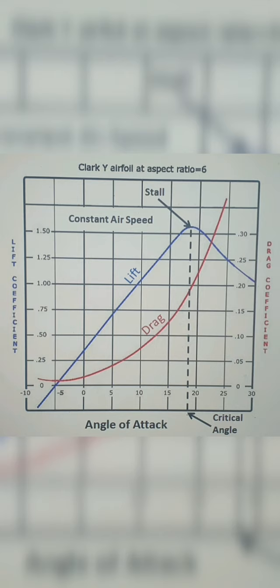Since the lift generated by an aircraft wing is proportional to the angle of attack and also to the square of the aircraft speed, the same lift can be accomplished by flying at a higher speed with a lower angle of attack. Reducing the angle of attack also reduces the induced drag due to turbulence, thus enabling greater aerodynamic efficiency. Let us talk about the aerodynamic drag components.